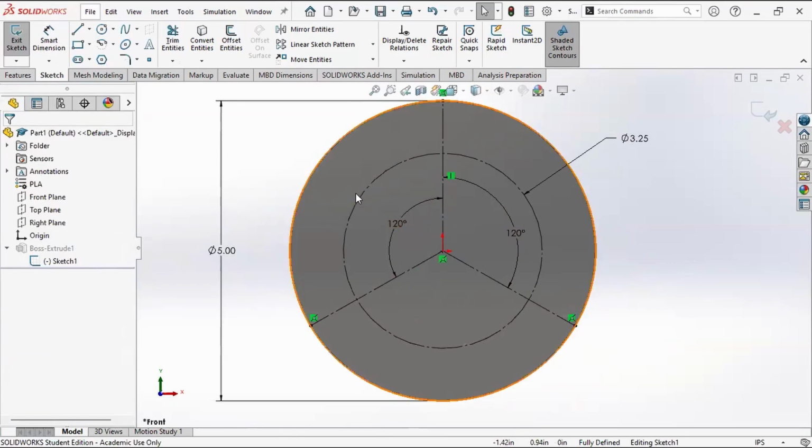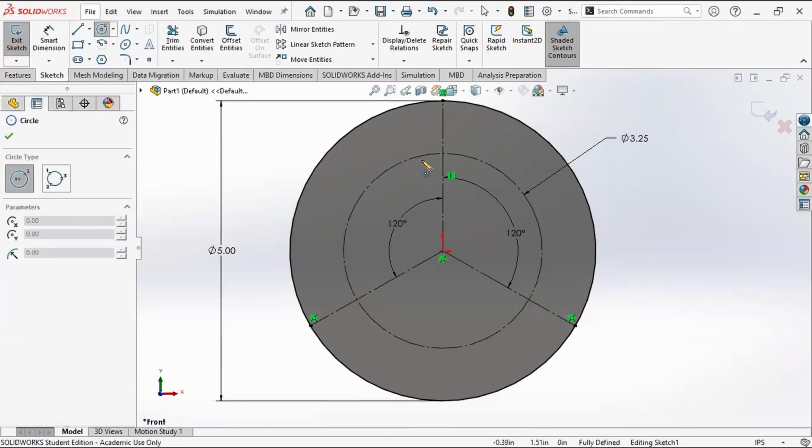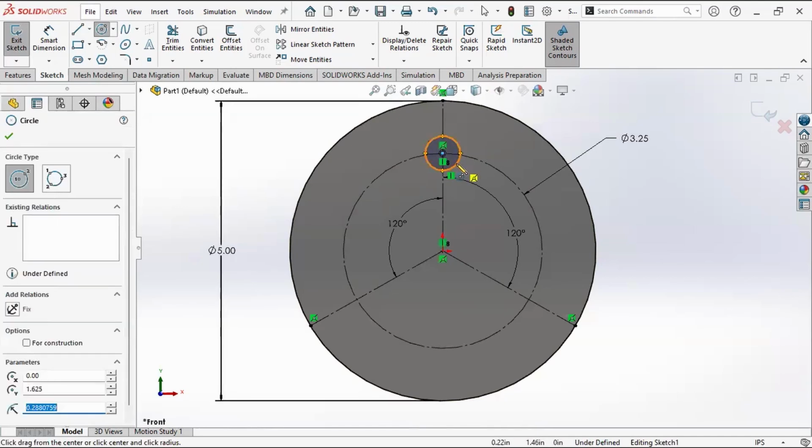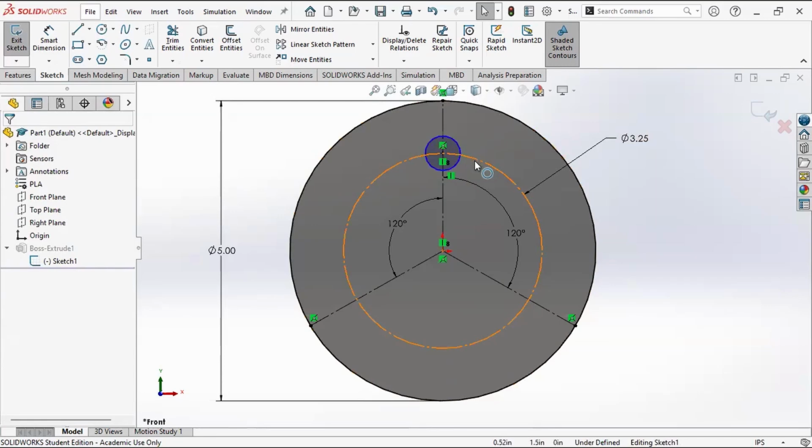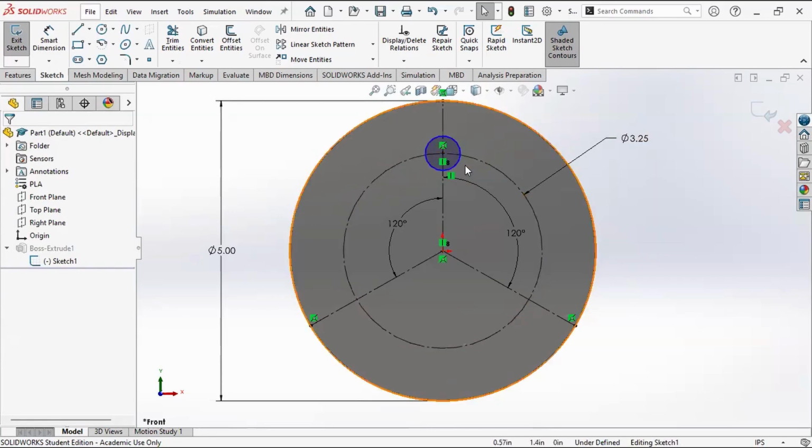What about the bolt holes, right? So the point of a bolt circle would be to actually create bolt holes. To do that, I can just grab a circle. And I notice I already get that automatic diamond point, which is a good start since I know I want the first one to be vertical, right? I want these holes to end up at the coincident point where this line meets this bolt pattern circle.